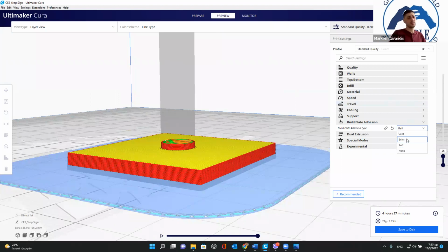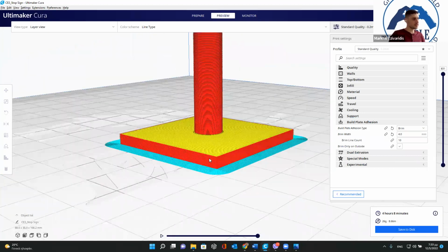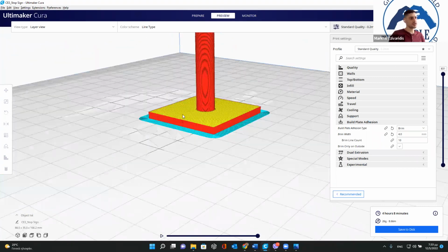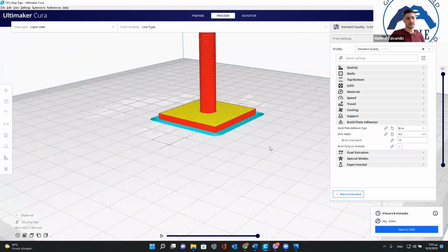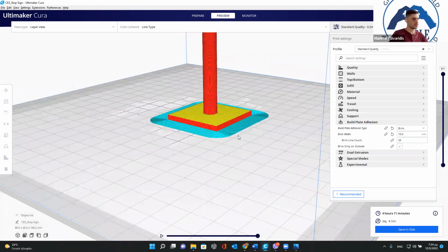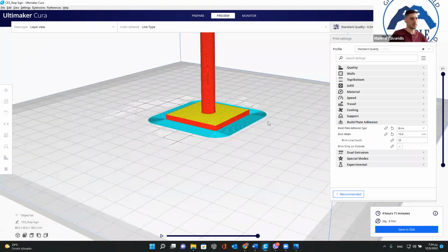So in most cases, what I use is the brim choice, because you may detach it very easily, and it's also great for the stability of your model, and you can readjust it. You can make a 10 millimeter base, which is a big one. Obviously, you won't have any problems with this one.